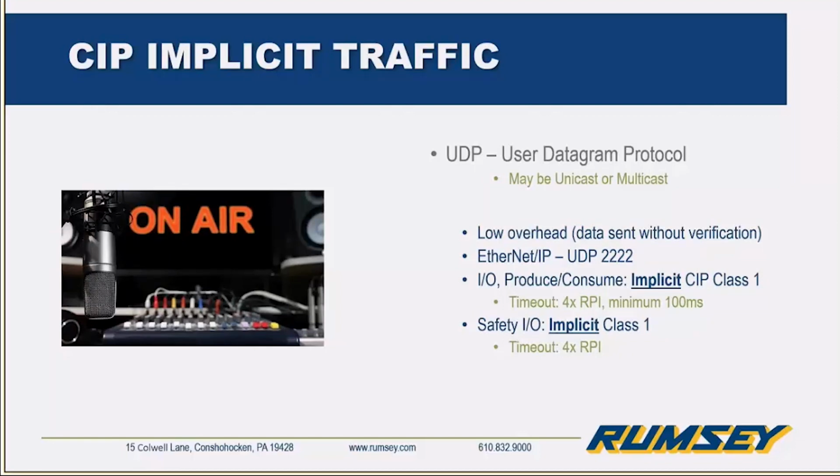Pay particular attention to the timeout values here. The default is 4 times the RPI, or requested packet interval. Rockwell hardware defaults at 20 milliseconds, meaning a timeout, or communication loss, will occur at 100 milliseconds, or 4 times the RPI.